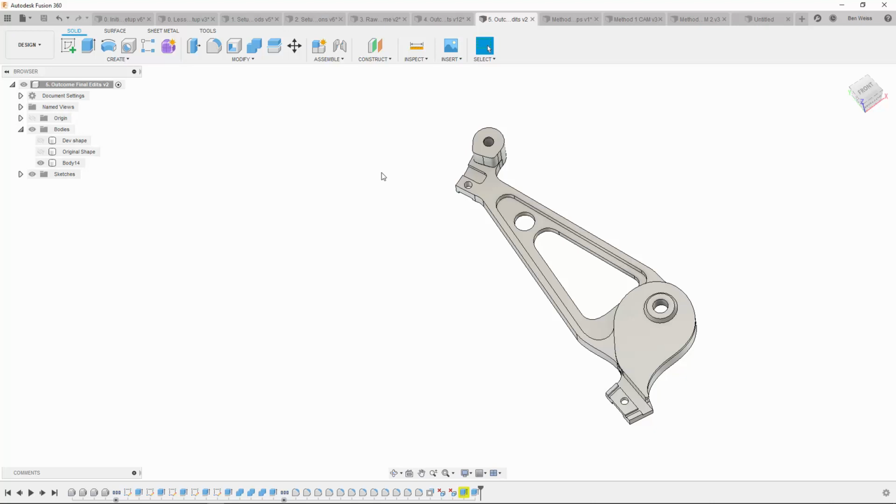I forgot one bit of my geometry, or one comment. Back when we were adding a line, we replaced a part of the spline with a line. It turns out we can do the same thing for arcs. So we can take a spline arc, put a real arc on top of it, trim away the spline, and have the arc take its place. The procedure is exactly the same. The handout describes how to do it.